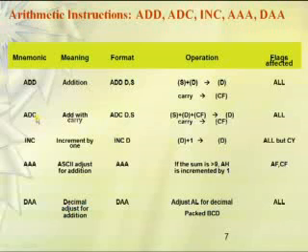For example, as this is a 16-bit microprocessor, if we want to perform 32-bit operations, like addition between two 32-bit operands, then we have to use ADC. Why? Because the carry that is coming out of the lower word should be added to the higher word addition. So in those cases we would be using ADC. ADC D comma S performs addition between source, destination as well as the carry flag, and the result is stored inside the destination register. If you get any carry, that carry gets copied into the carry flag. All the flags will be affected, depending on the result which we got.